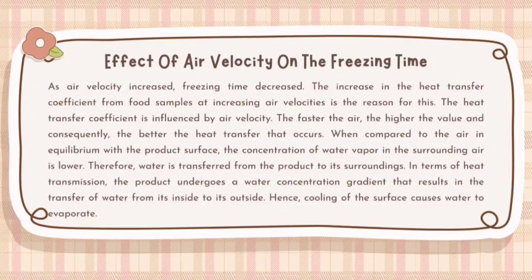When compared to the air in equilibrium with the product surface, the concentration of water vapor in the surrounding air is lower. Therefore, water is transferred from the product to its surroundings. In terms of heat transmission, the product undergoes a water concentration gradient that results in the transfer of water from its inside to its outside. Hence, cooling of the surface causes water to evaporate.